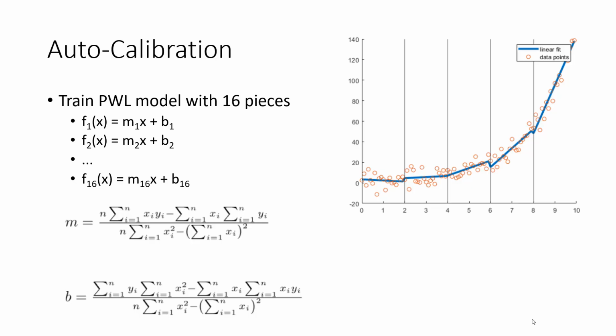And the segment you're in is defined by the input that you read. You read from the ADC, and it will give you a reading that you will then marry up to a segment. You have to use a lookup to figure out what segment it's in. Once you figure that out, you apply the linear model based on that segment.